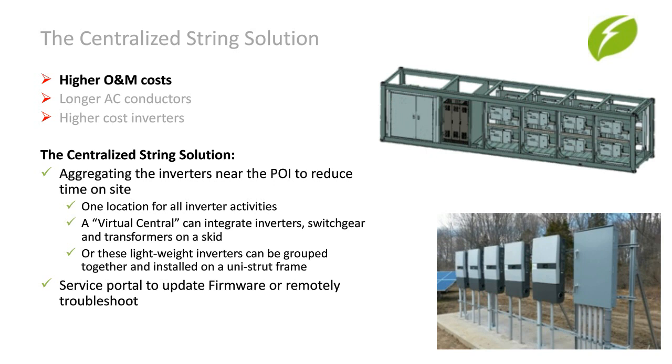I cannot stress this enough. Whether distributed or centralized, make sure your inverter can communicate with the manufacturer remotely. Troubleshooting and firmware updates performed remotely can greatly reduce the downtime in truck rolls. In the past, around 50% of service actions were related to firmware updates and improvements.